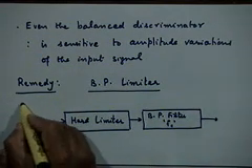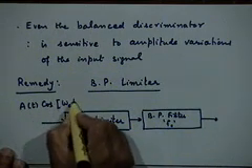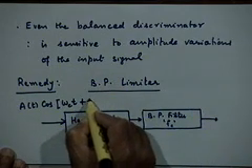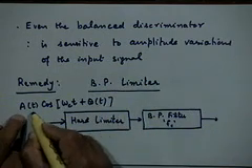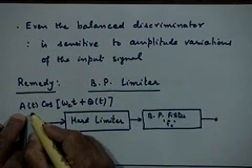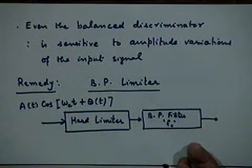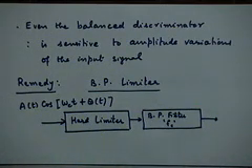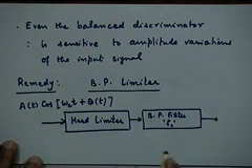So, the input to this is a signal which not only contains your angle modulation, that is cosine of omega c t plus theta t, but the instantaneous amplitude, which should have been a constant value, may have some variation with respect to time, which we want to kill, because if you do not do that, the ds tilde by dt and s tilde t that are present in the relationship that we discussed will produce at the output some component which is not proportional only to m(t), but also additional variations because of these things.